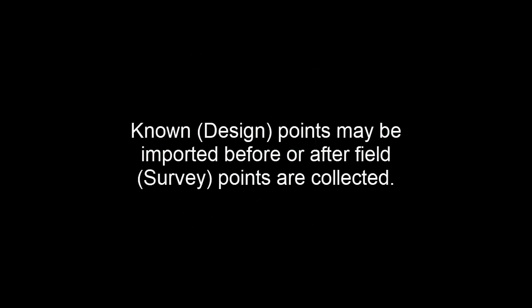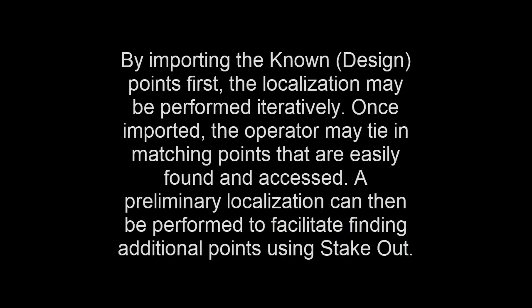Known, or design points, may be imported before or after field survey points are collected. By importing the known design points first, the localization may be performed iteratively. Once imported, the operator may tie in matching points that are easily found and accessed. A preliminary localization can then be performed to facilitate finding additional points using stakeout.